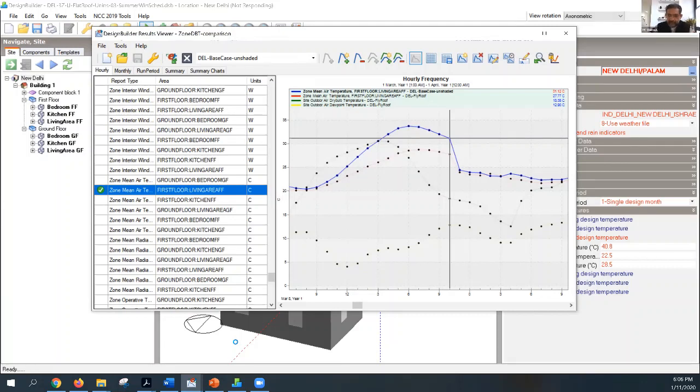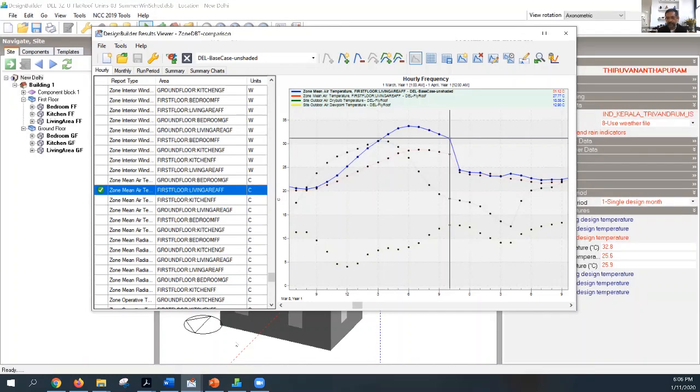Yes. Now within EnergyPlus, there are some equations that talk about moisture migration through constructions. I haven't personally tried them, but I've heard from people who've tried them that it is the fastest way to slow down your simulation by a factor of 10. So use with caution and please read the manual on that. If you look for moisture migration through materials, it's there. Okay. Next question.